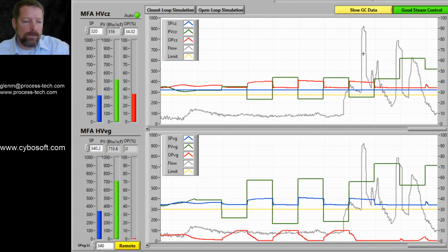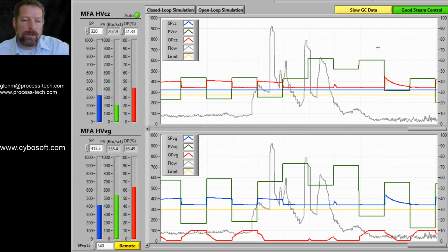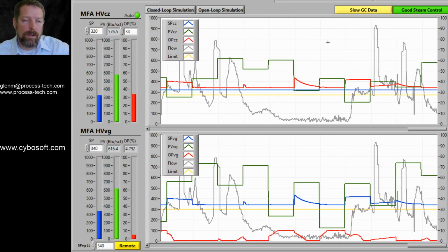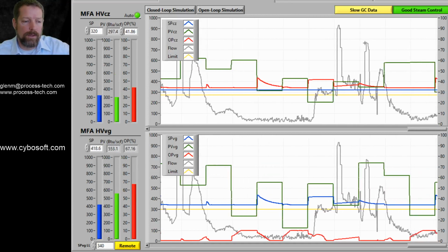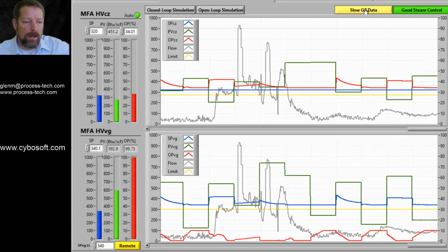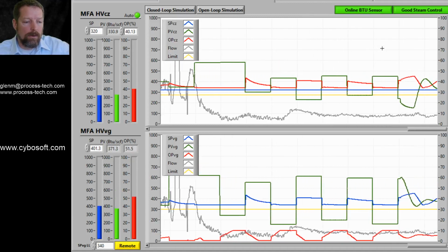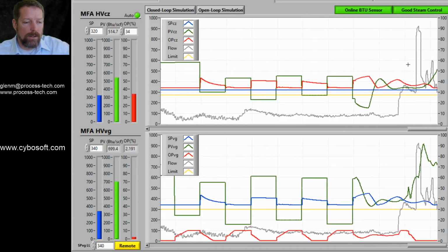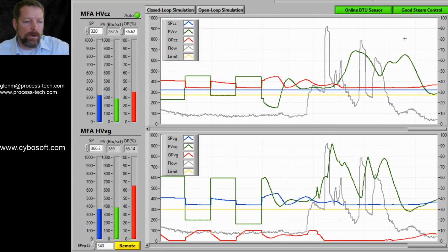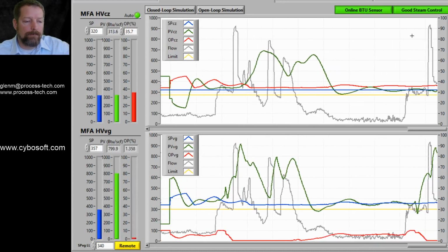A gas chromatograph is simply not fast enough from a process control perspective to give you the resolution that you would rely on for doing good process control. So although a lot of customers have GCs and they work great for what they were intended for, getting a fast net heating value is just simply not a viable solution. So switching that back off, you'll see the square wave that is the time that it takes for a gas chromatograph to get net heating value has returned to a much more fluid flow rate, or rather fluid measurement.